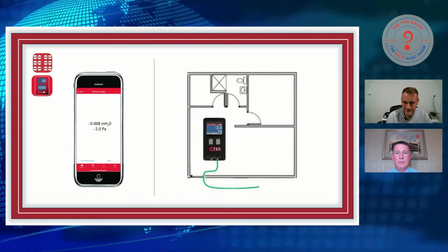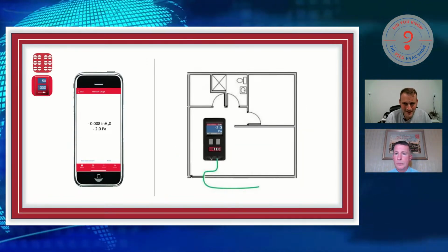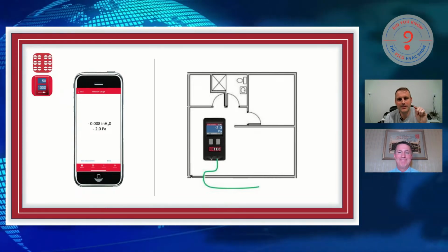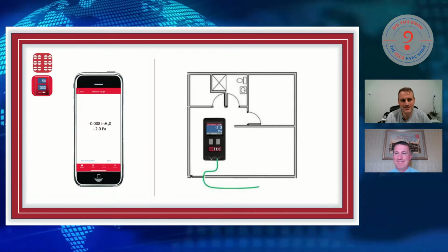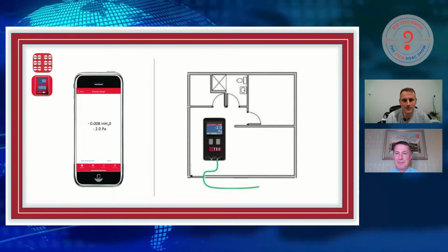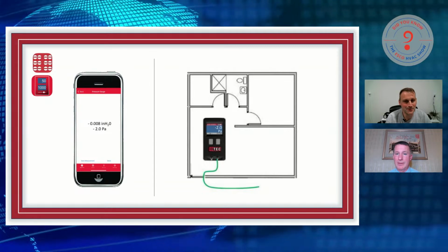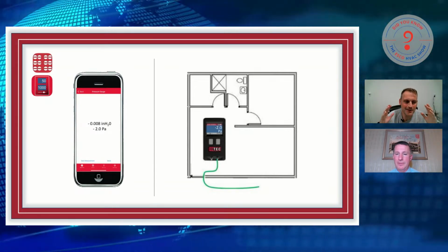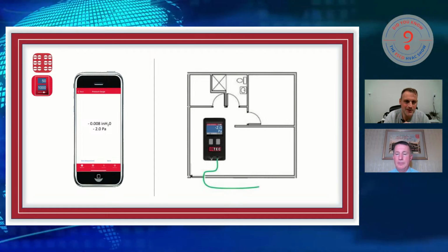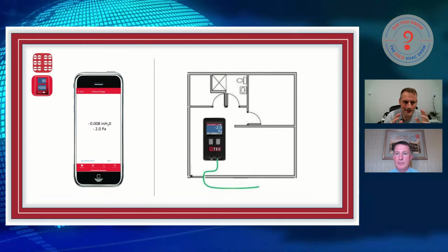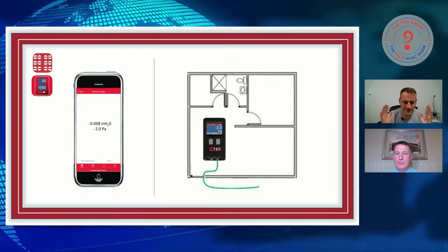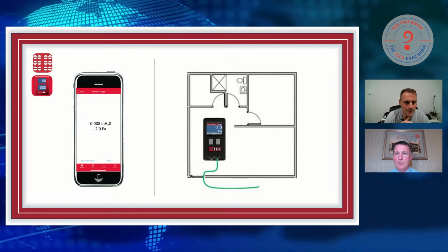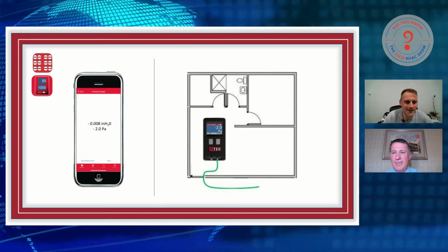Okay. Here's one that's really building sciencey. But if you get to learn it, and if you're in the chat and you want to challenge yourself and you haven't heard us talk about this before, give it a go, because this one's fun. This is where you have an air conditioner with ductwork outside the thermal envelope, and let's say you've got dominant supply leakage. Let's say the return is sealed up really good. Single box return, lots of supply ductwork, and the supply ductwork's leaking 200 CFM. Bunch of attic ductwork.